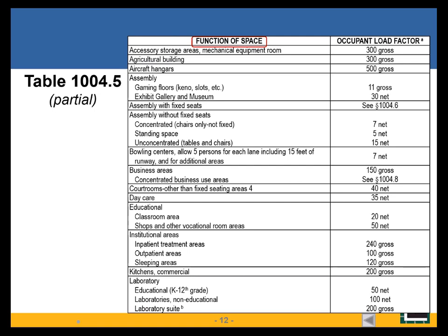Keep that in mind, because don't get misled by the titles there and think they're referring to occupancy classification, because, and this is just a portion of the table, many of them say educational, oh, Group B, institutional, oh, Group I. Oh, wait, my Group B ambulatory care facility will fall into there too. So look at the function when we're looking at this.